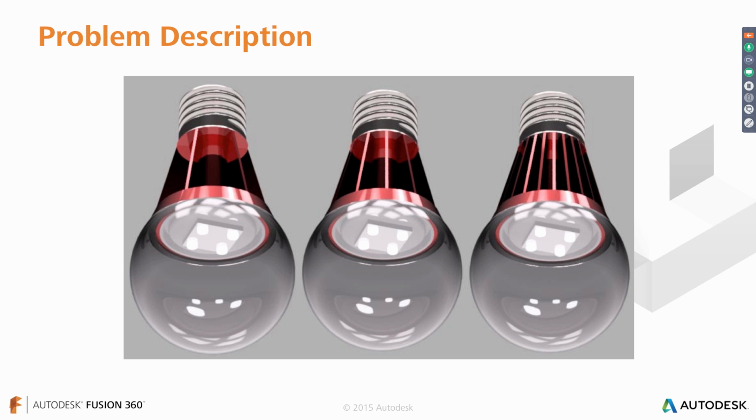So what I wanted to try to do was to test multiple iterations of this bulb, right? The reason for that is, if adding 50 fins to my heatsink has a diminishing return, then we don't necessarily want to do that. We want to keep the cost as low as possible. So using simulation, we can get that cost benefit analysis very quickly and very easily to understand if the changes we're making are going to be effective, and if they're going to be worth the cost, right?